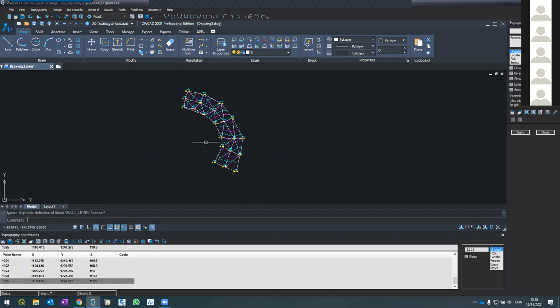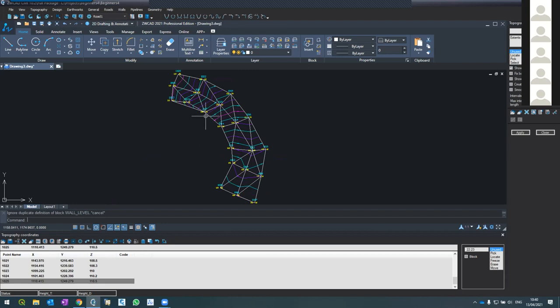Okay. Questions about what I just explained? Any questions? So again, the problem is what we call border problem. The software creates triangles with an edge which are longer than what we want. The solution goes to the maximum interpolation length, enter a value and press apply and see the result.